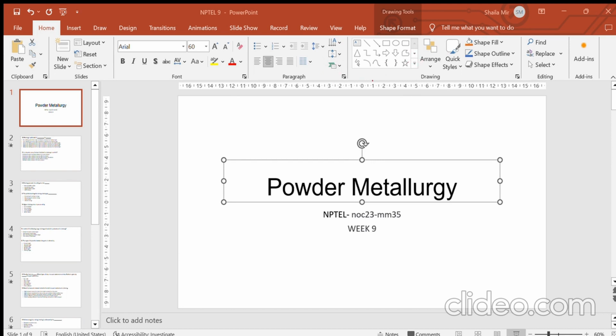As it moves from green density to sinter density, the pores that were present inside the material are being closed, because now you are having grain growth during sintering, and that grain growth results in interactions between the grains, and then they lead to the collapse of your pores, the collapse of any spaces inside the compact, and as a result you have strength. So the shrinkage takes place in the material, that means whatever the material dimensions you have taken, that will shrink because of this collapsing of the pores inside your material.